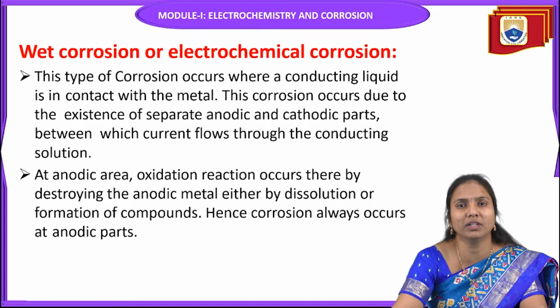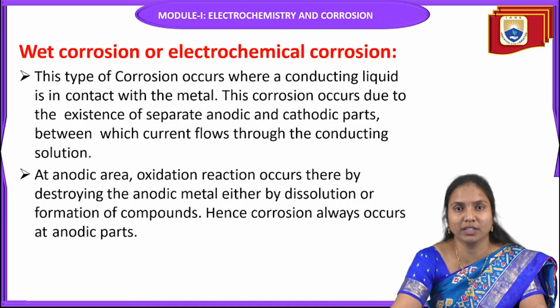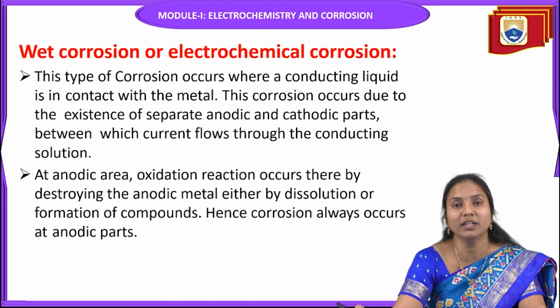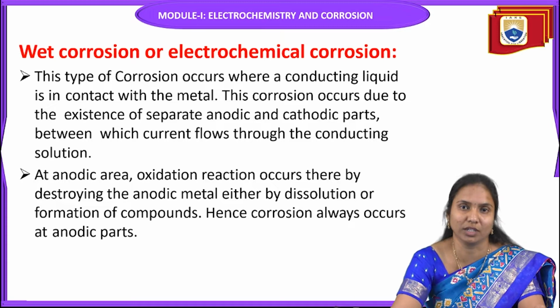So what is the Pilling-Bedworth rule? If the volume of oxide is greater than the volume of metal, in this case it acts as protective. If the volume of oxide is less than the volume of metal, in this case it acts as non-protective.